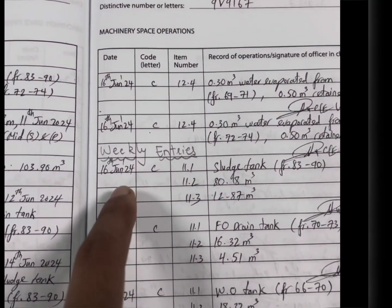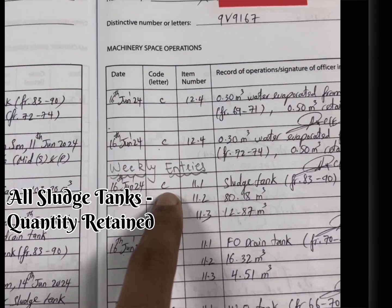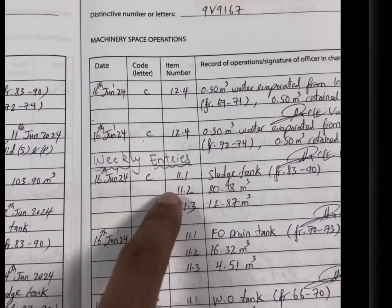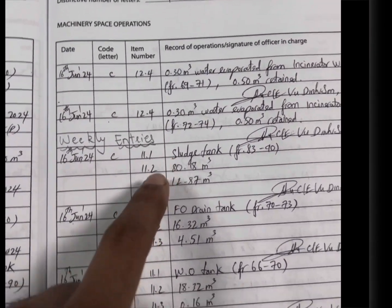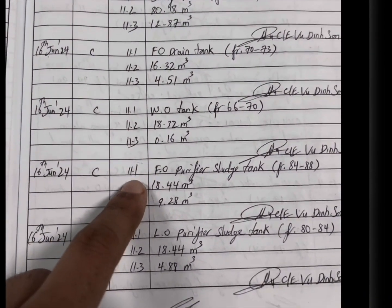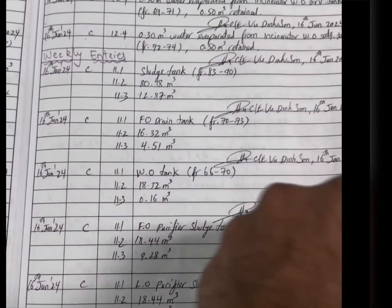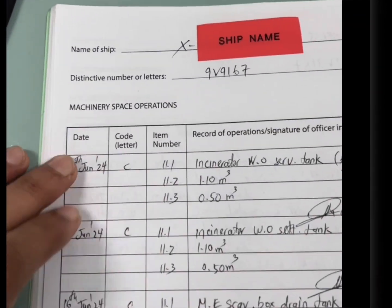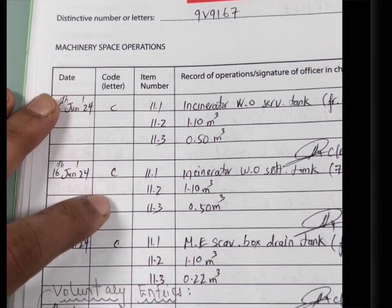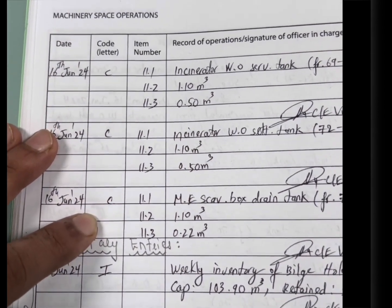Coming to the weekly entries, it has to be in the format of code C 11.1, 11.2, 11.3: flush tank, fuel oil drain tank, waste oil tank, fuel oil purifier flush tank, lube oil purifier flush tank, incinerator waste oil service tank, incinerator waste oil settling tank, and main engine scavenge box drain tank.